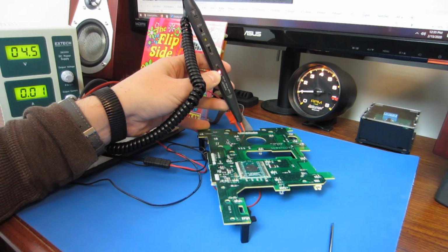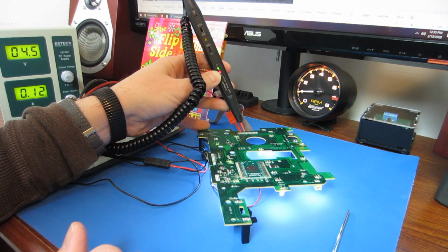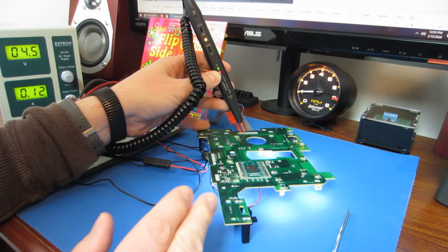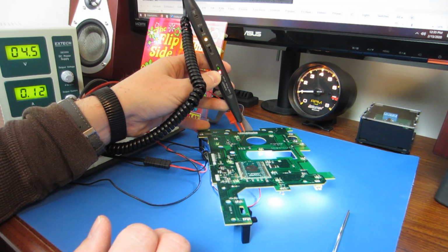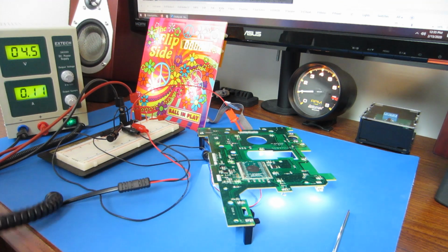We lost power because it timed out. And it looks like that MOSI pin goes high when we lose power. Let's bring it back. Yeah, as these LEDs change, the tone changes. That means, I'm guessing, that the bits on the SPI bus are changing, and that's causing the logic probe to sound a bit different. Interesting.